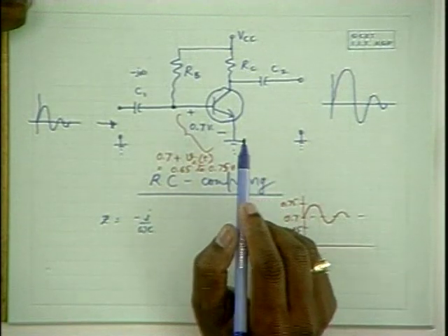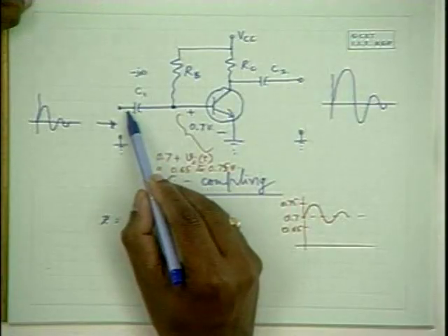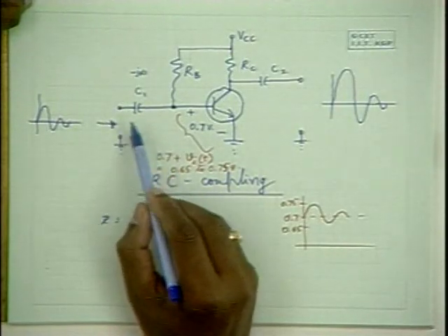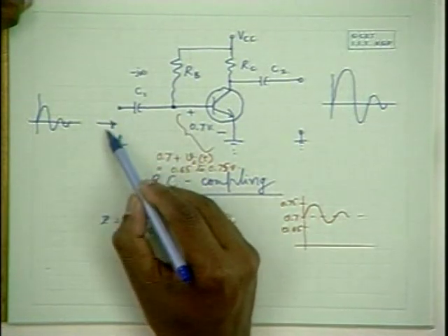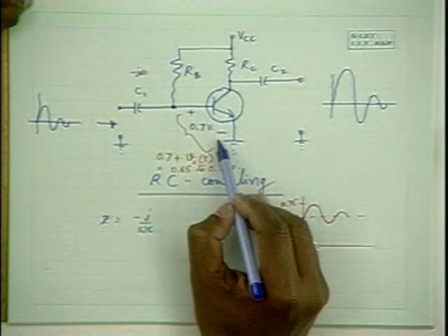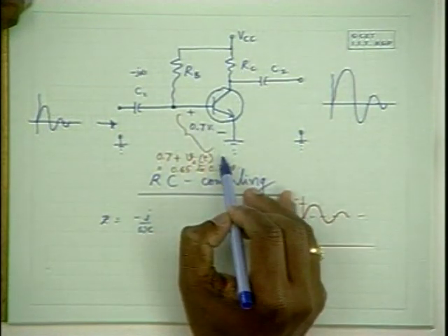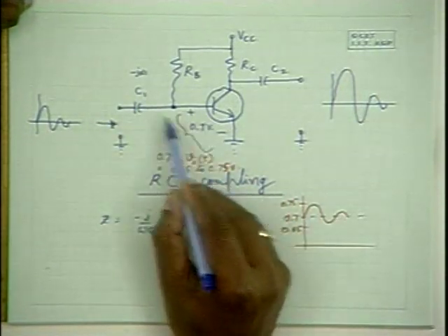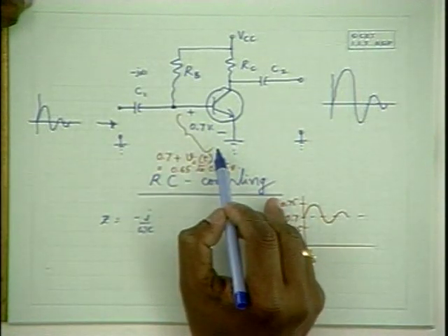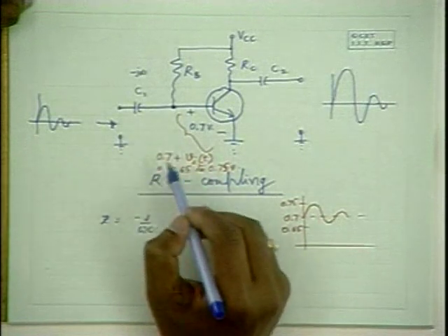Yes, there is a question. When we are applying a signal of high frequency, it acts almost like a short circuit, so why doesn't the current pass through this? So the question is, at high frequencies this acts like a short circuit, so why does the current pass only in this direction? Please note that it's alternating current, and we have the source on this side, an alternating signal. There is no alternating source on this side. It's only some load resistance. Therefore, this voltage divided by this resistance plus this impedance plus this impedance is the current, and that current flows in this direction.